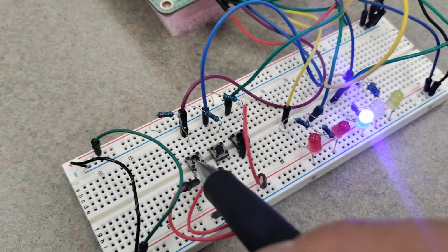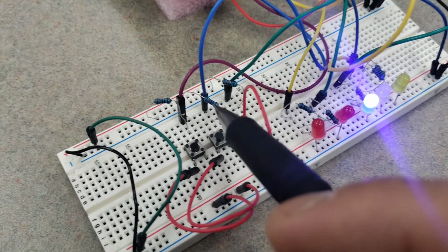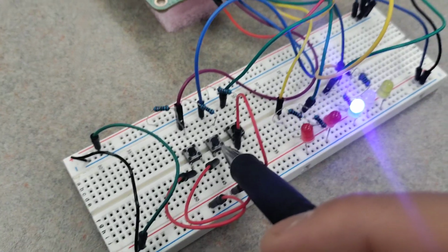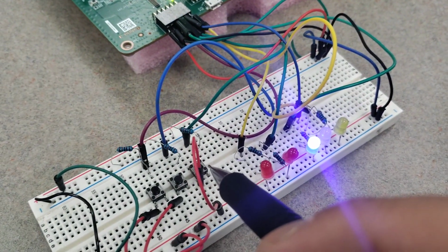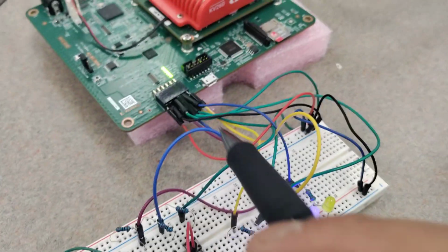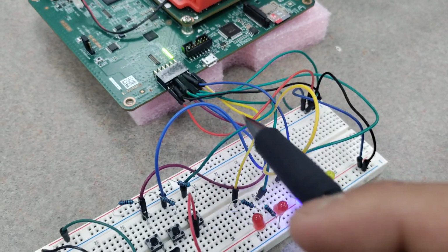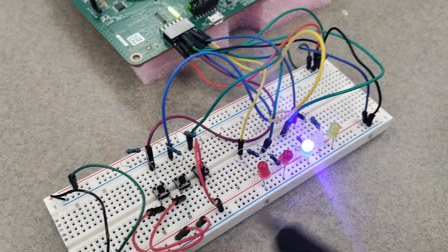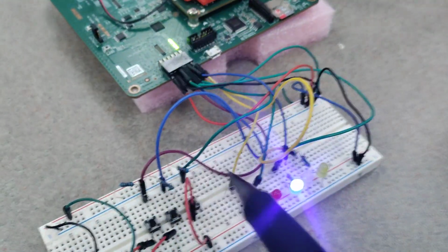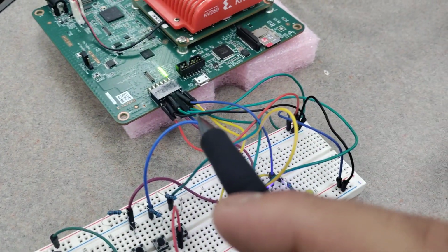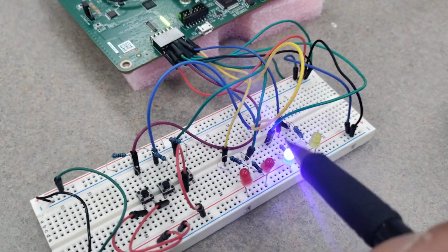So for these pins, this first button is mapped to pin number 7. The second button right here is mapped to pin 6 on the board. And this last button right here is mapped to pin 5 on the Kriya board. And the Kriya board supplies us the 3.3 volts for positive voltage that enables us to power this circuit. And we have ground connecting to the Kriya board as well. So the Kriya board is supplying our input-output pins as well as our positive voltage and ground.